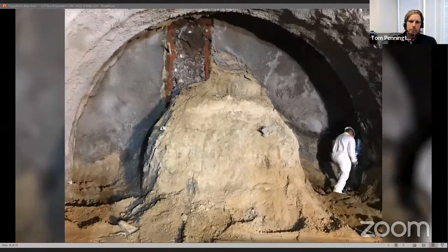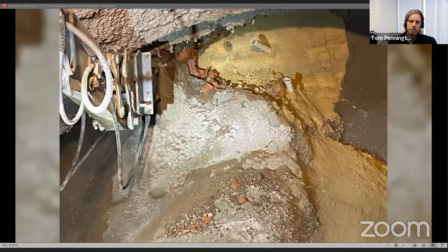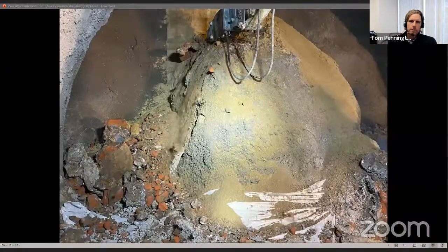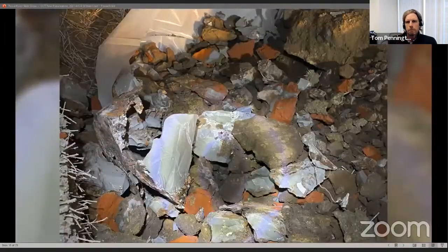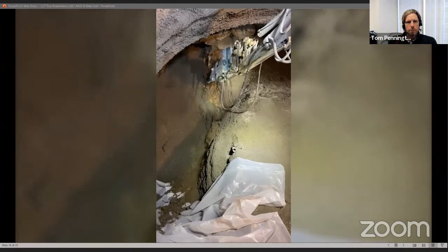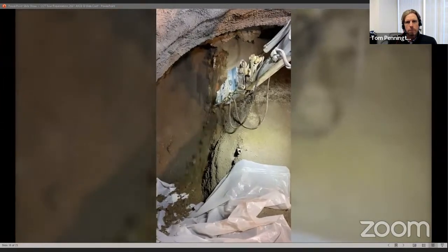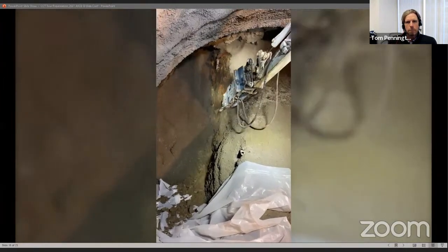The major concern was that the pit contained loosely compacted materials with significant voids that would collapse into the tunnel once the brick lining was removed, causing an uncontrolled chimney behavior up to and under the building foundations above. After a review of inferred geometry of the brick anomaly, a grouting campaign was initiated. Holes were drilled and a grout mixture was injected to fill the voids and stabilize the materials inside the trash pit.